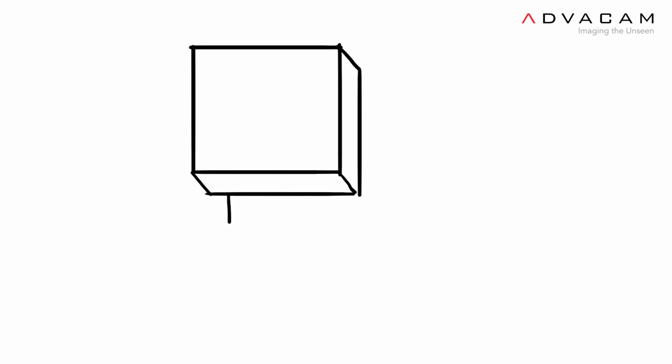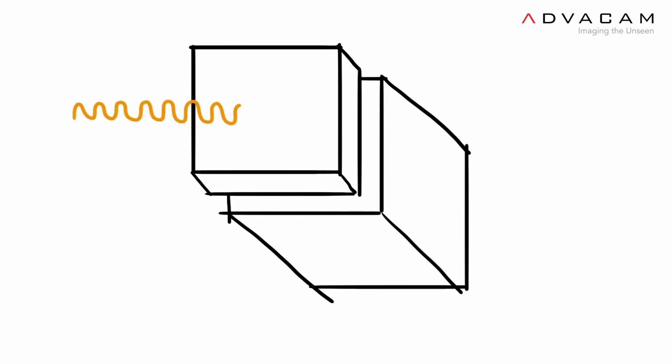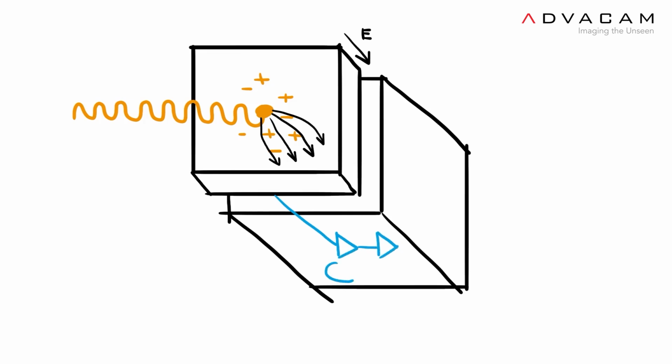The first layer of a photon-counting detector is a semiconductor sensor. When a particle hits its surface, it creates an electrical charge, which is then transferred to the electronics in lower layers. It passes through an amplifier to a counter, which stores a complete amount of hits during exposure and ignores noise. To make sure the counter only receives relevant data, we can set a threshold for a certain signal strength. This allows us to select only the photons which generate the clearest image and uncover hidden details.